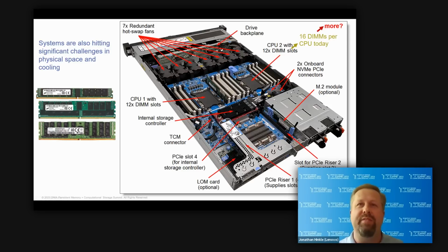And one of the things we've done just to be able to fit this number of DIMM sockets for the number of memory modules is we've spaced them closer and closer together. These are mostly air-cooled systems, and so as the air goes down between the DIMMs, it's harder and harder to get the air to flow, and it's harder to get the heat out of the memory modules. And so plugging more and more DIMM sockets and DIMMs in there, it's harder and harder to cool.